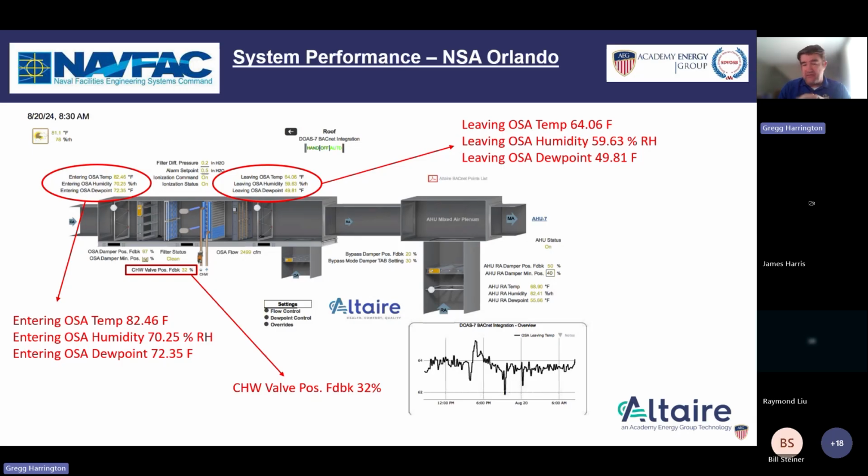So based on this scenario, the loads coming back on the return air side, we were able to do all of the conditioning on just the outdoor airstream component, so that when it mixed with the return air, as it went through the air handling mixed air coil, that mixed air coil for this scenario at this time was not doing any work.